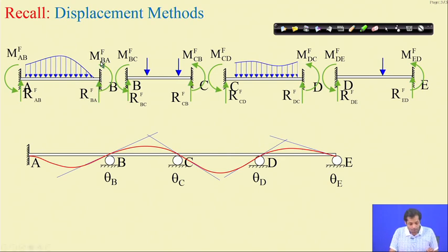Then, in the actual structure, in addition to the externally applied load, there will be deformation. In the first part there is no deformation, and in the second part we have only deformation. In the actual structure, both happen together, we have forces and deformation. Therefore, whatever reaction force you have will have two contributions. One contribution is from the first part, the kinematically determinate structure, only due to the external load, and another contribution is because of the deformation of the structure.